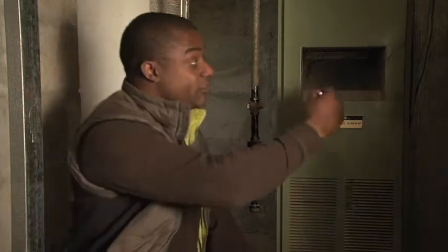We're going to check the flue pipes. Do we have any problems with the flue pipes, like they're not attached properly, we see rust and that sort of thing. Next, we're going to take a look at the draft diverters. Does the draft diverter on the furnace, is it free of obstructions? Does it have anything off in there? We want to make sure that that's out of the way.